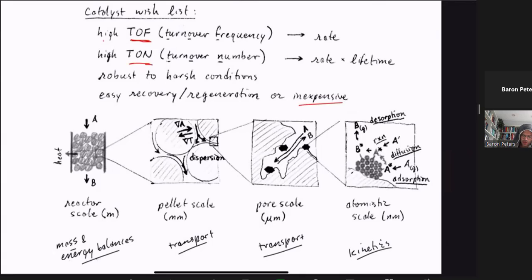But also there are internal heat transfer and mass transfer processes occurring inside these particles. And that can lead to gradients where maybe the interior of a particle is hot and the outside, this interstitial space, is relatively cool. Or, for example, where the concentration of a reactant at the surface is very high and the concentration in the center of the particle is very low, has been depleted by all the reactions happening between the surface and the center.